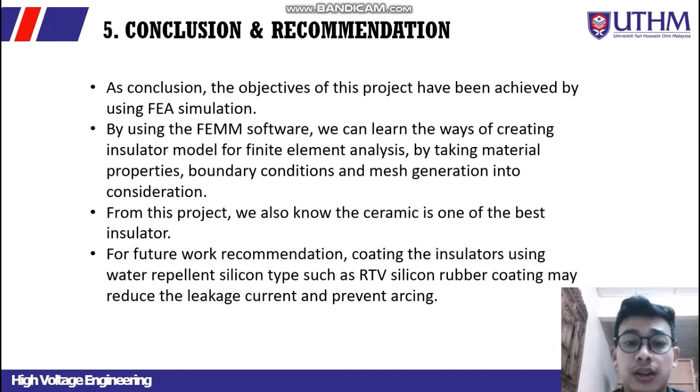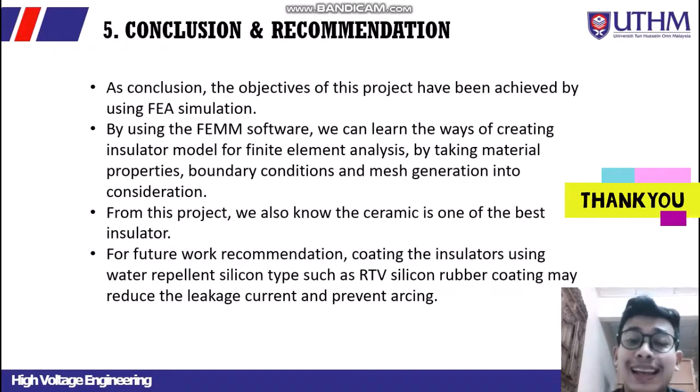For future work, we recommend coating the insulator using a water repellent silicone type such as RTV silicone rubber coating, which can reduce the leakage current and prevent arcing.